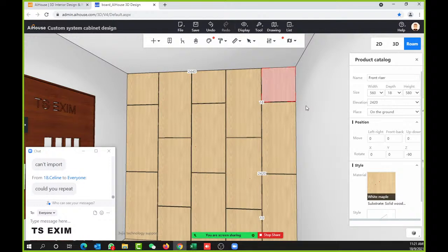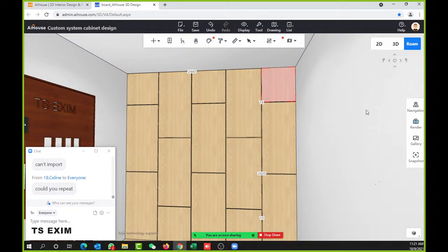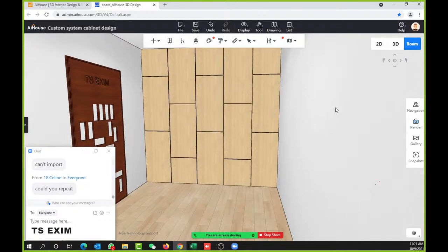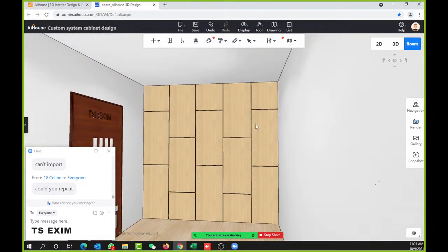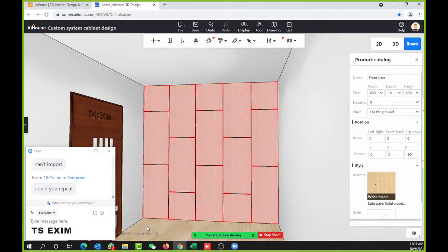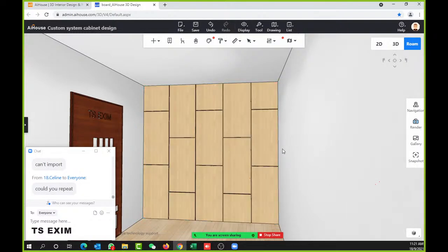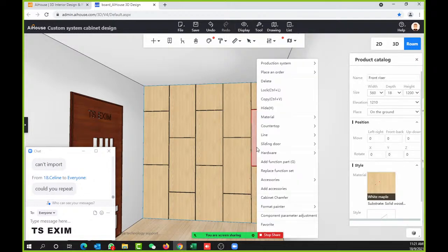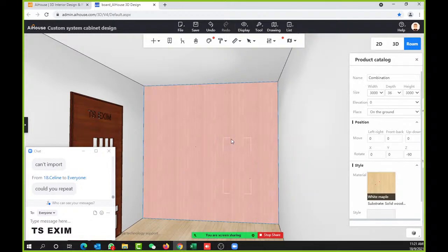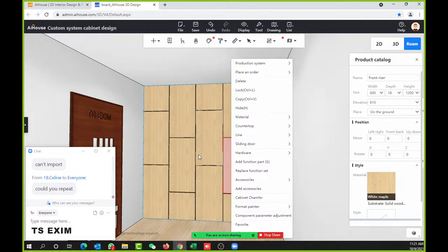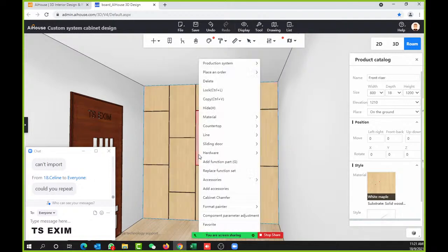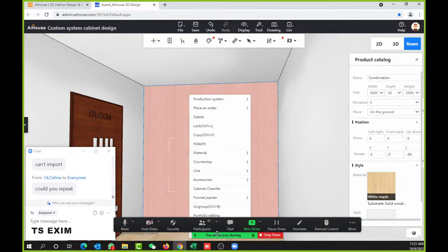Okay, time's up. So this wall panel we created, right? We can save it. Next time, if you have a similar wall or you want to edit it, you can use it back. You can hold the Control button, select it, then press Ctrl G or right click also. Or we can copy it and right click. Shift select, right click.